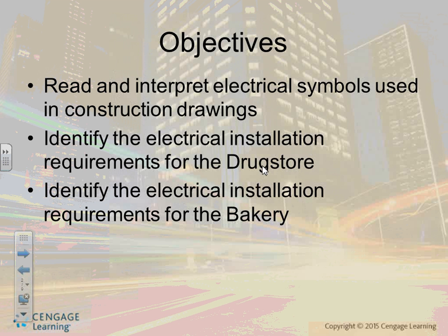In Revit, guys, let me tell you what Revit does. When you put your stuff in Revit, you will be able to generate all this. When you finish your work and send it to the architects, you should be able to generate everything you're looking at from the model, including your lights. That's why it's so important to put your light in the right location. Imagine if this light, in the elevation, shows right through the door. The architects are not going to hire you next time. If you know BIM, building information modeling, you have to pay attention to the height.